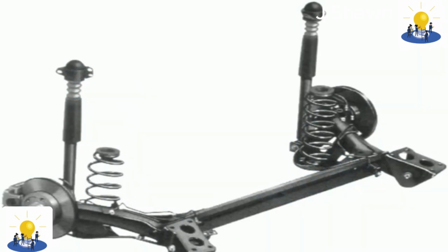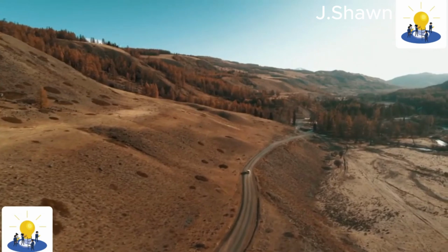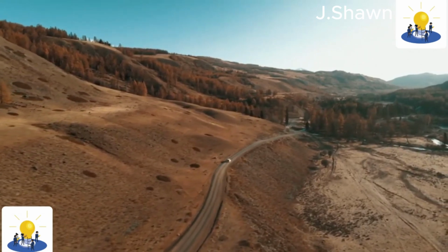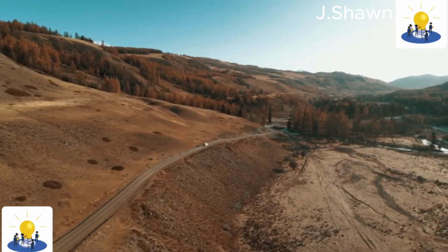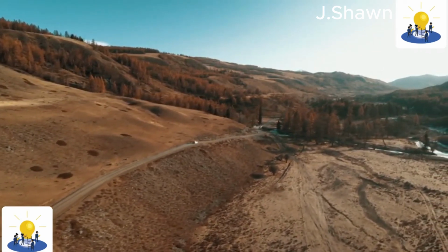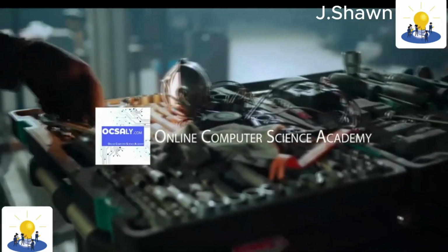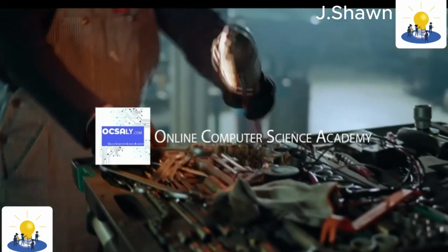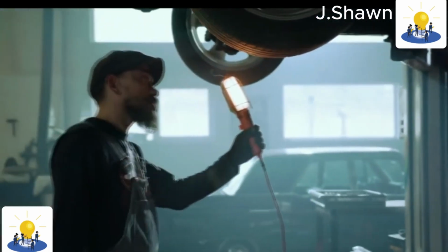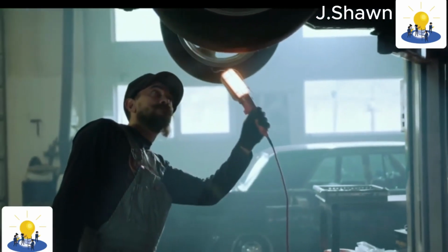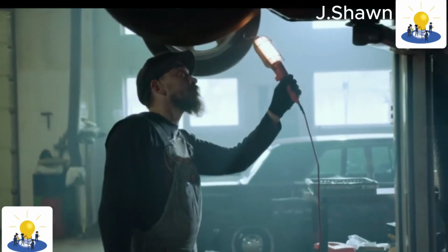Front beam axle suspension is unusually sensitive to any lack of concentricity in the hub and wheel assembly, which can cause a side-to-side oscillation, shimmy, of the steering at certain speeds, typically 60 to 80 kilometers per hour, commonly referred to as death wobble within the 4x4 community. This is addressed on some vehicles with steering dampers, although removal and careful refitting of the front wheels often cures the problem.